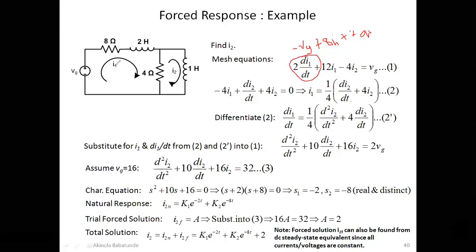All right, then the current passing through 4 ohms would be plus 4 into bracket, because the current coming here is I1. You know that from our previous analysis and discussion. I2 is also passing through the 4 ohms, going up. I1 is flowing down. I2 is flowing up. So that means the voltage across these 4 ohms will be 4 into bracket I1 minus I2. Okay. So everything has to be equal to 0.